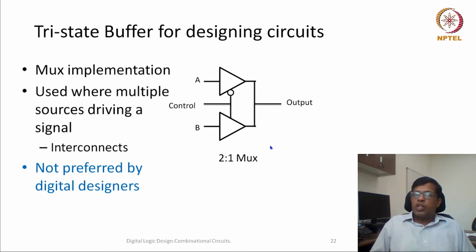So usually whenever we are doing verification, in the simulation, whenever we see X somewhere, that means unknown values, or we see Z somewhere, that is a trigger point that there is some error. And those errors can be recognized easily, and then we can start fixing them.